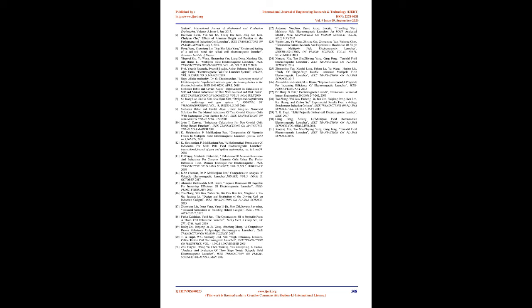The acceleration coil with pulse current induces eddy current in the projectile. The authors proposed a multistage twisty multipole electromagnetic launcher structure in which the second stage of coil is twisted by some angle to the first stage for better performance. It results in larger accelerated speed and magnetic torque of rotational motion, and less transverse displacement of the projectile.